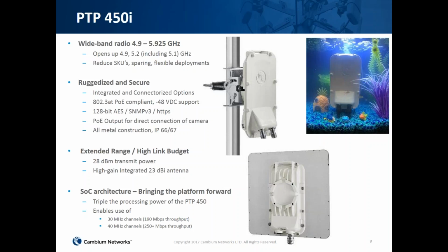It has that aux port for PoE out, and that means you can power a camera or a Wi-Fi access point that uses PoE. I can actually power that off of the auxiliary port, saving a switch port and saving some additional cabling. So again, a much easier and simpler, cleaner deployment.